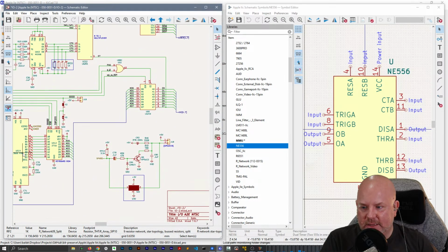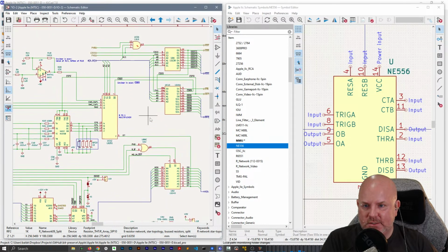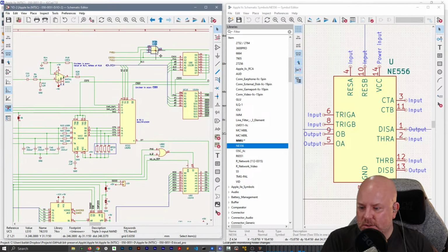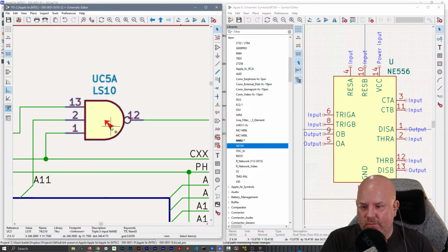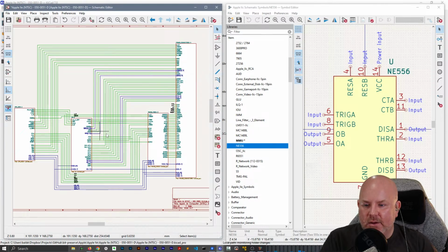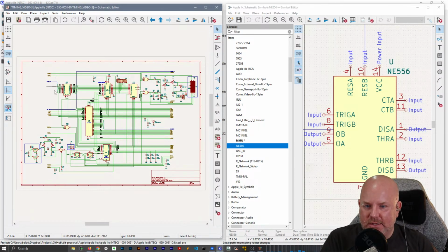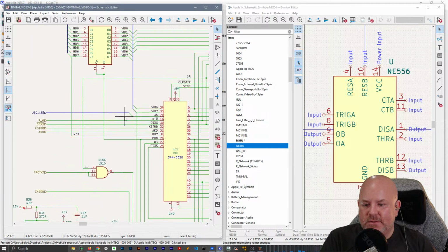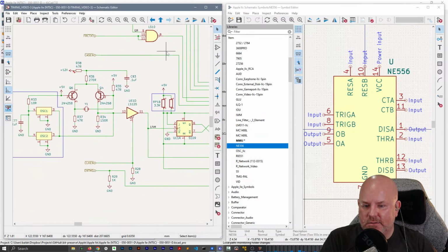All right, so we got that chip, this filter, and then the rest of this glue logic is probably okay. What is this error up here? So I'm going to try to click on the symbol. Input has input power pins and units that are not placed. Yeah, okay. Well, I'm not going to worry about that probably tonight, but we got to figure something out about that. Okay. We'll just keep going. So 373, one of those things.